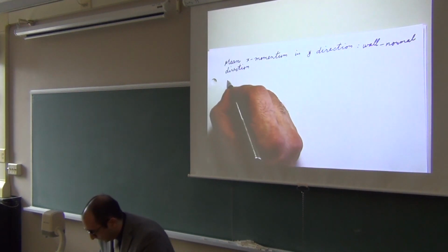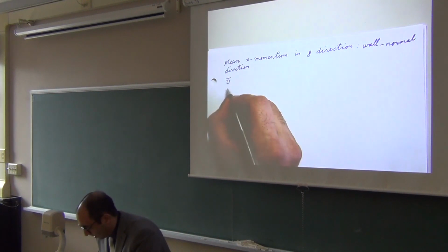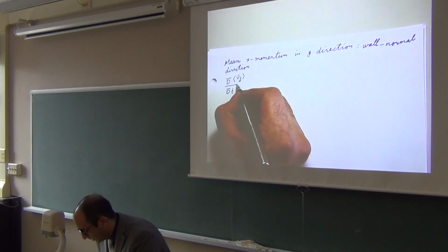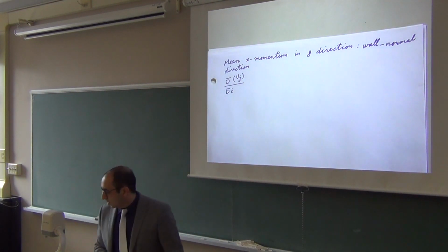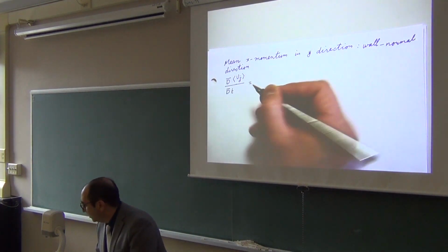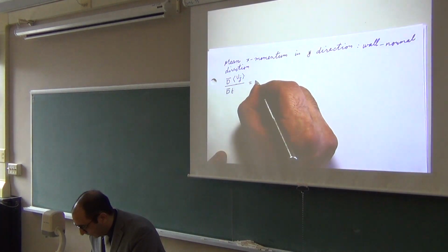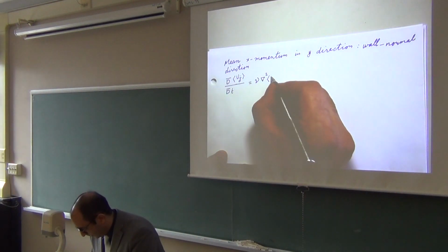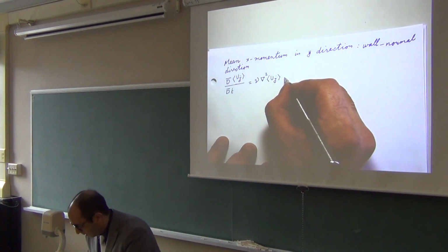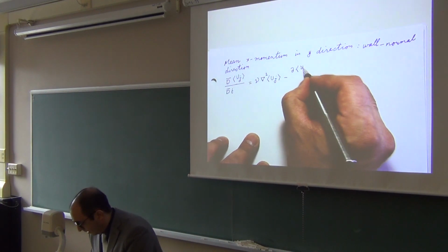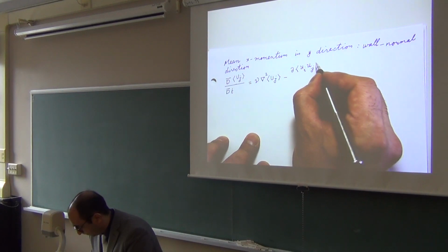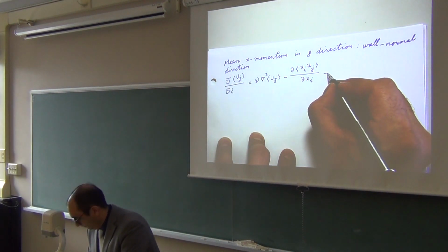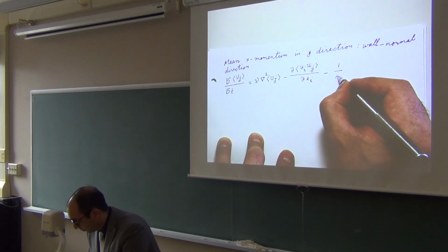I'm going to start with the Navier-Stokes equation. So I start with the total derivative. And I could write this for any component of the momentum. Let's say I was writing it for uj. Total derivative of the mean momentum, j direction, is kinematic viscosity Laplacian of mean momentum in the j direction, minus the Reynolds stress, ui uj, partial xi, so have that one, minus the modified pressure term.